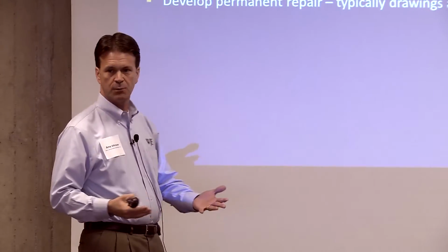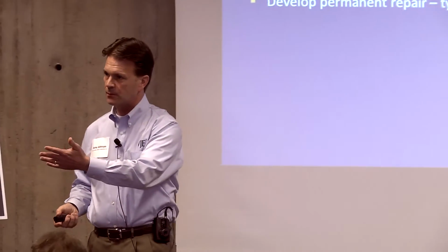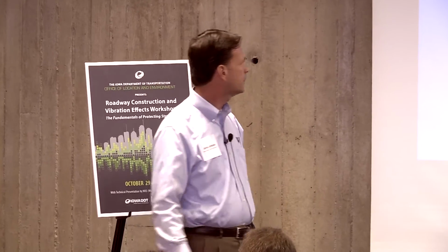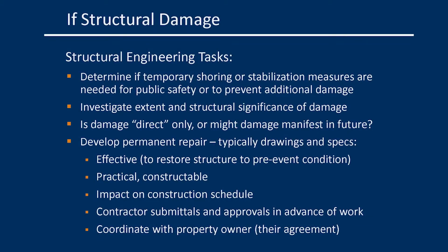So again, keep your thinking cap on, so to speak. It's not only what you see is what you get. It might be what's a logical possible effect, and then checking to see if it's there. And then determine a permanent repair. Typically, you're going to need some drawings and specs if it's structural damage.